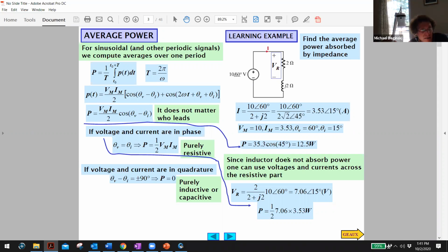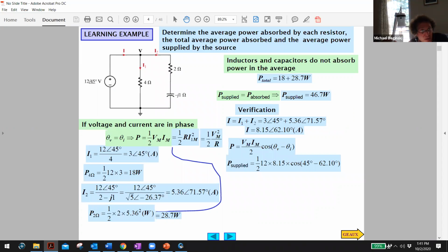Yes. All right, next one. Here, the circuitry gets a little more complicated, but the essence of what I'm going to ask will not be. It says, determine the average power absorbed by each resistor and the total average power supplied. Well, there's 2 things you worry about. Whatever is absorbed by all the elements of the circuit is supplied by the source. Y'all hear me? Now, I can be more formal about it if there's 2 sources, but for now, whatever is supplied is dissipated. It's that simple. There's no mysterious storage device if you're in steady state.